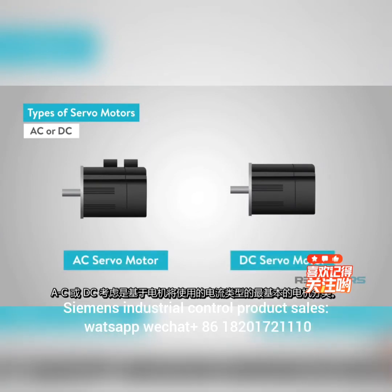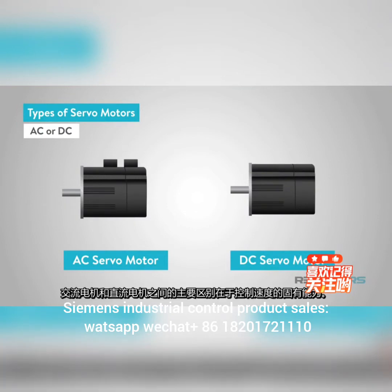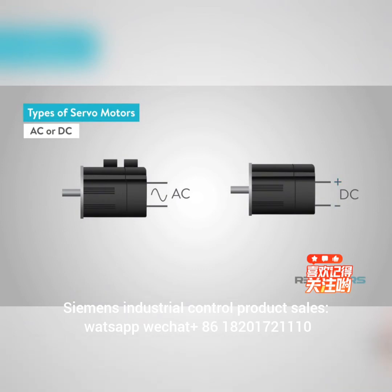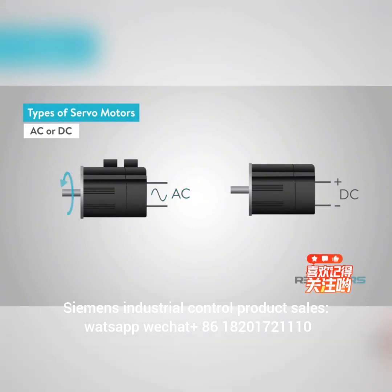AC or DC is the most basic classification of a motor based on the type of current it will use. Looking at it from a performance standpoint, the primary difference between AC and DC motors is in the inherent ability to control speed. With a DC motor, the speed is directly proportional to the supply voltage with a constant load, and in an AC motor, speed is determined by the frequency of the applied voltage and the number of magnetic poles.